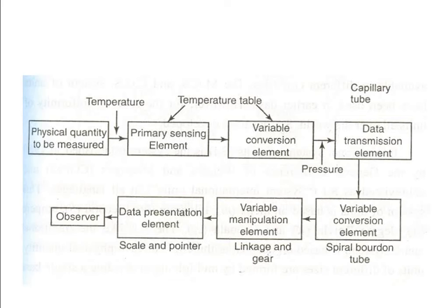So the liquid or the gas which is being filled is being sensed by the temperature bulb, and then it is being converted into the pressure, and then the pressure is being transmitted into the capillary tube, and then once again it is being converted and manipulated and presented to the observer.